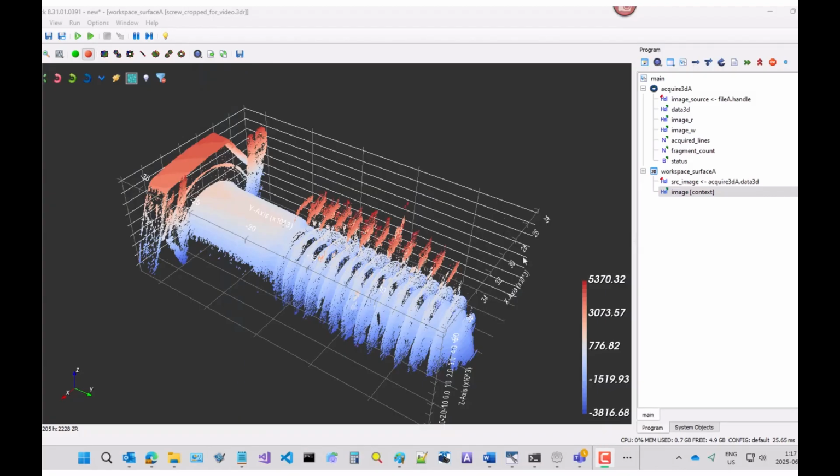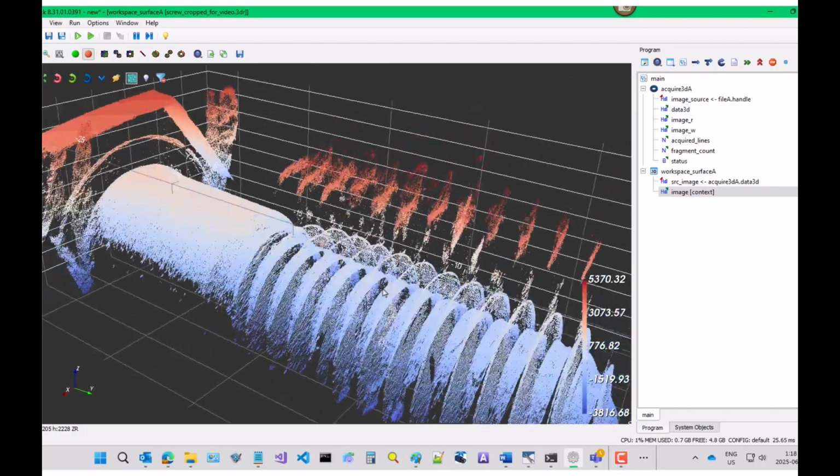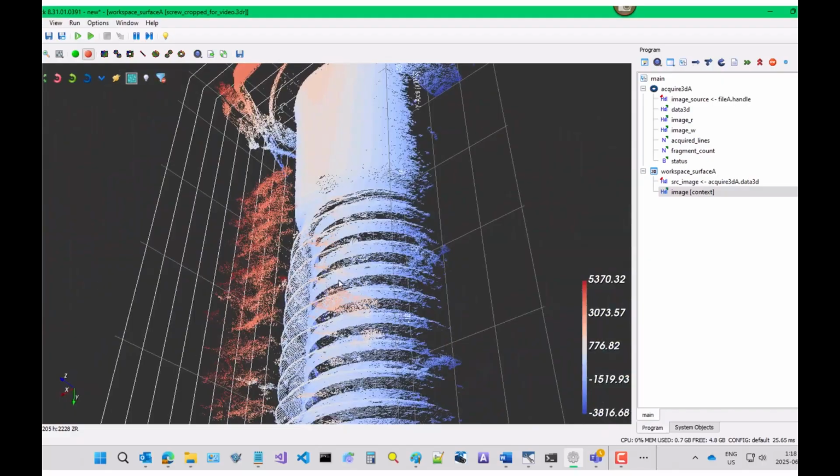When scanning objects with a Z-Trak profiler, the laser light is reflected back to the profiler sensor and the height of each pixel along the x-axis is calculated. However, depending on the type of material being scanned and its shape, the laser light may be reflected, creating artifacts of non-existent points. Shiny or metallic surfaces are particularly prone to producing scattered reflections.